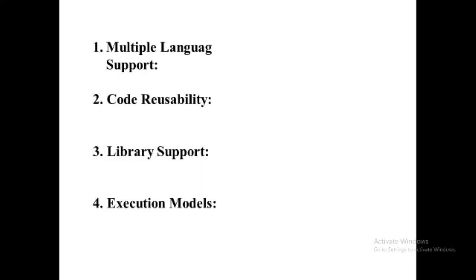There are two ways of entering the program. Number one, direct program entry to the program memory, that is RAM, plugged into the central controller. For this purpose, the programmer is connected to the processor or the programmer interface module. And second, programming the EEPROM submodule in the programmer without connecting it to the PLC, that is offline. The memory submodules are then plugged into the central controller.